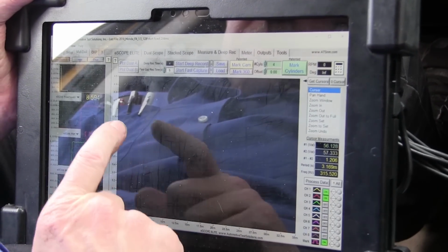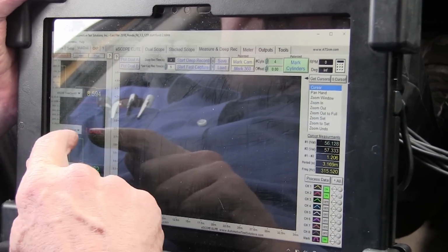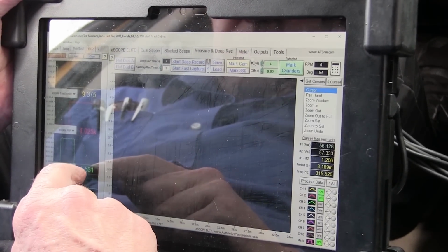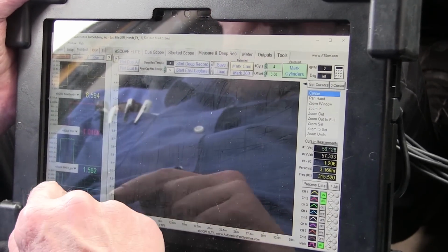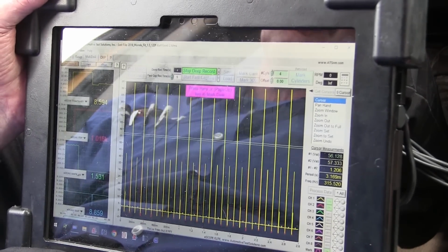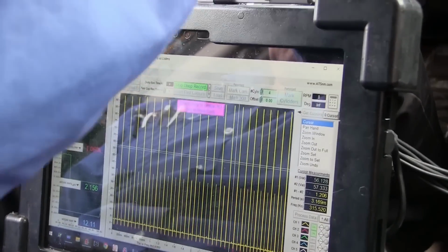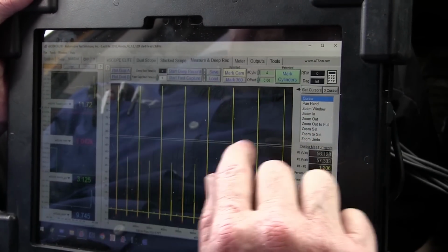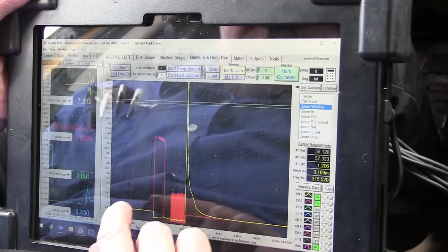Okay, guys, I want to run some scope tests, but right now I've got total trim over here. The fuel pressure is right behind it, so we got about 500 pounds. And the gram weight is 1.5, 1.6 at the mass sensor. And my RPM's down here. So let's go ahead and get some data. This is the injector, same injector, number 2 injector. So first, let's just take a look at one of these just to see where we are now.